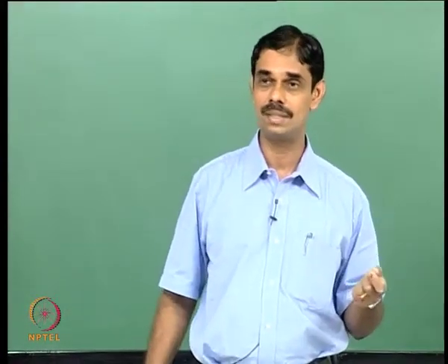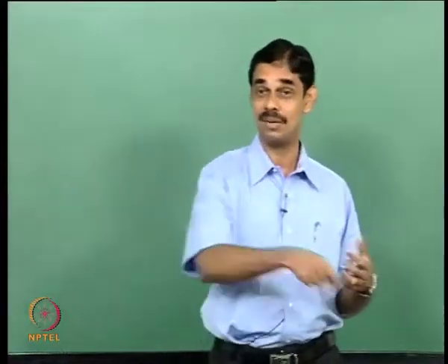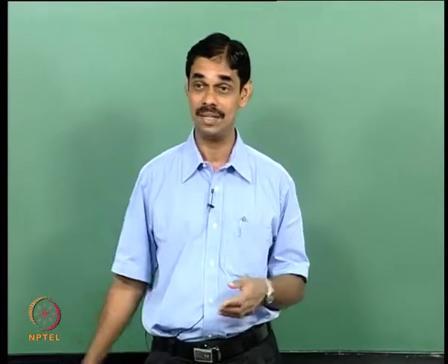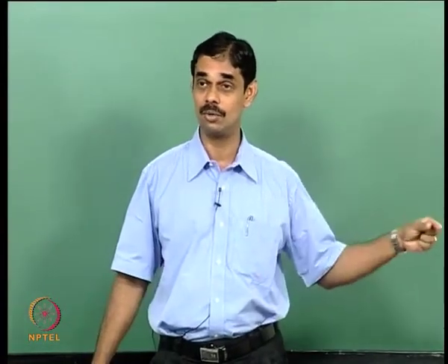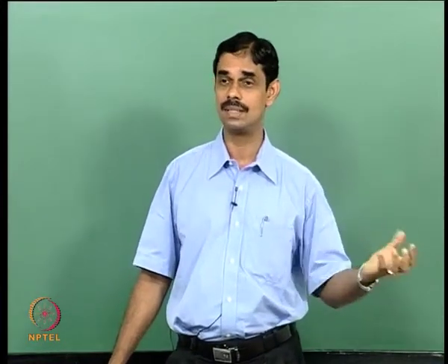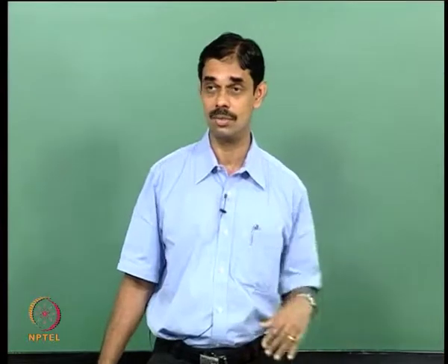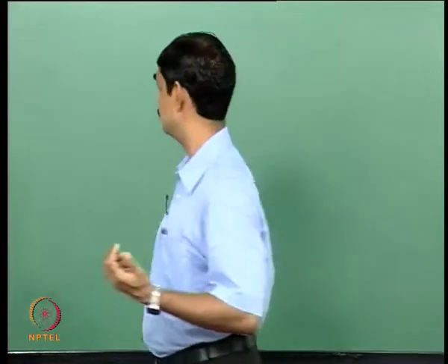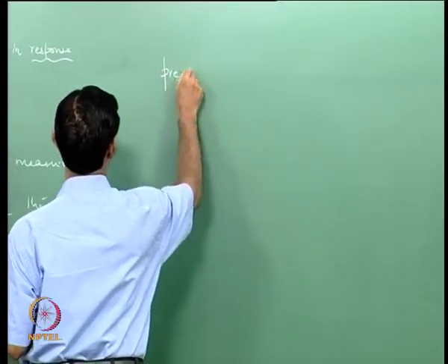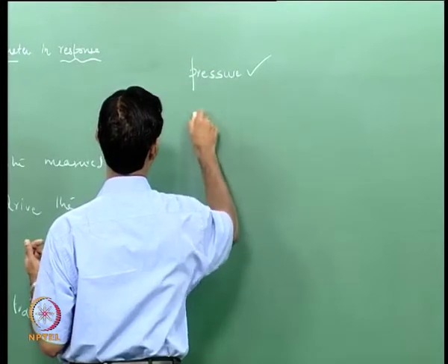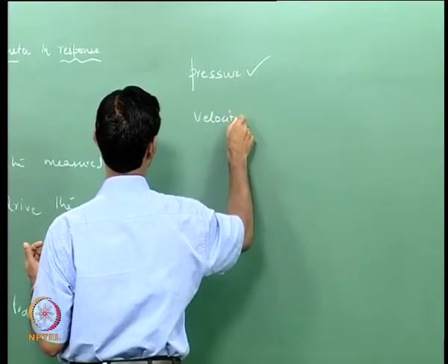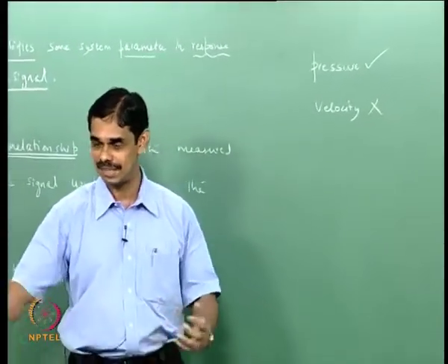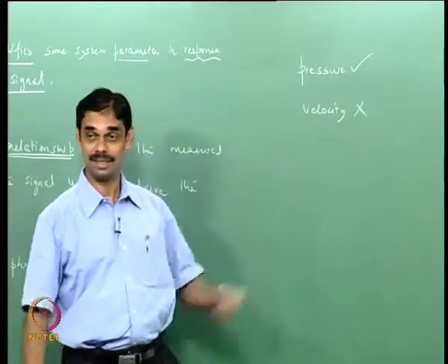If you put a hot wire in a hot zone, you wouldn't measure anything. You have to have a cold zone, and combustion is by definition hot. So some people in the laboratories use a hot wire in the cold zone, just to measure the fluctuating velocity at the base of the flame where it is cold. That is the best you can do. So in general we will not try to measure velocity. Pressure yes, velocity no. Of course there are people who have lots of money and lots of equipment, and just because they have it they may use it, but in general I wouldn't recommend this.